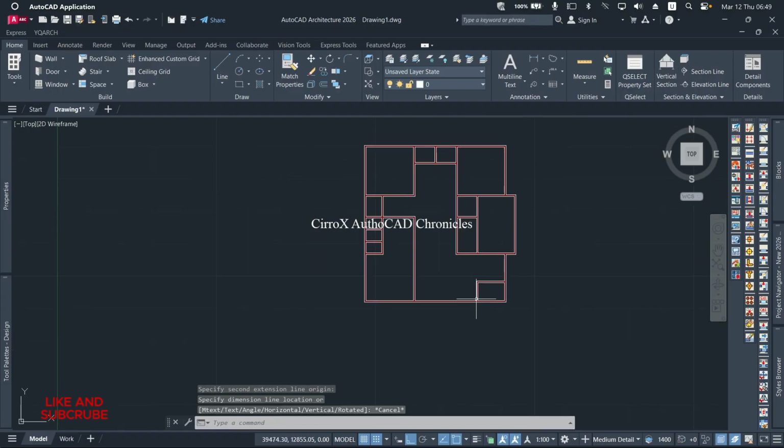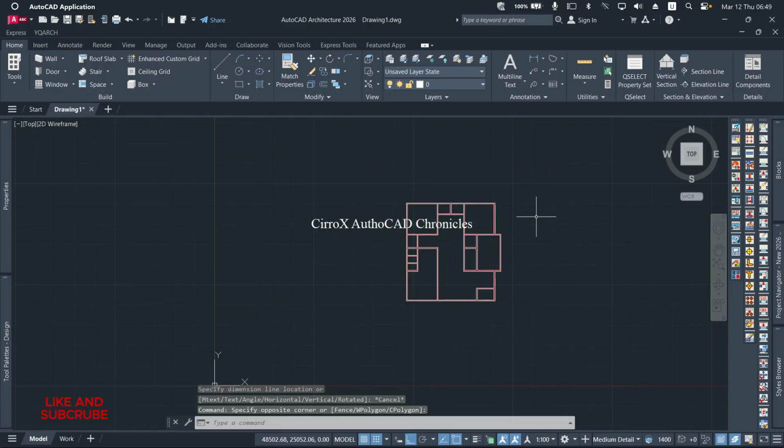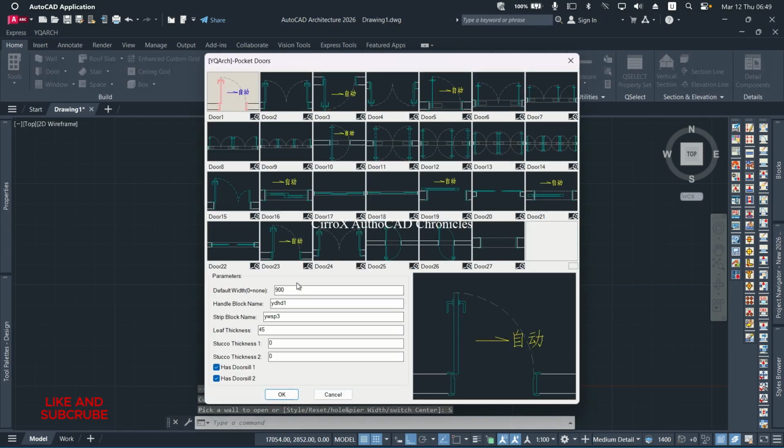Alright. So now I can go on and add in my doors and windows. To add in a door, a door is ADT, and I'm going to pick a style from here. So I'll go with this, and the main entrance door is going to be this.